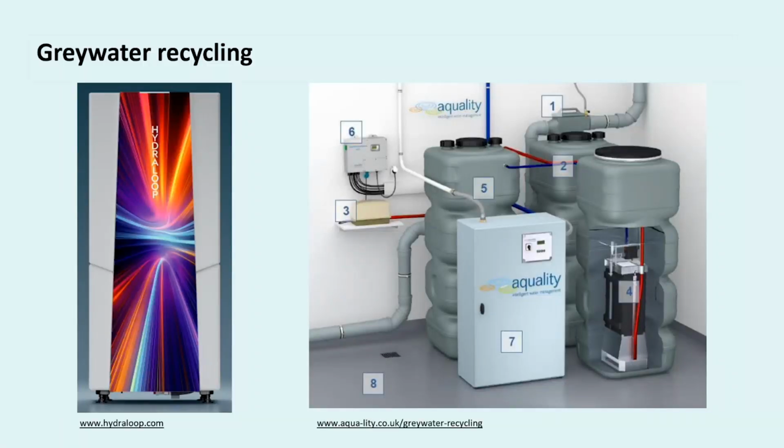So if rainwater or stormwater harvesting aren't suitable, the non-potable demand could be met by installing a grey water recycling system, as we've seen in our example of the home earlier, with 43.4 litres being captured every day. And as this exceeds the non-potable demand of 28.5, grey water recycling provides a consistent supply throughout the year, meaning that this approach is particularly useful in drier parts of the country.